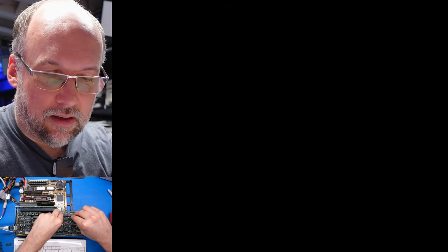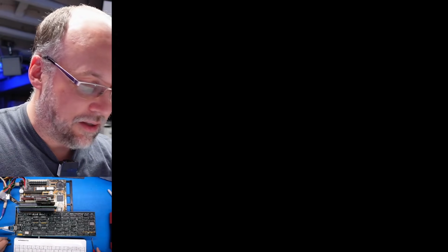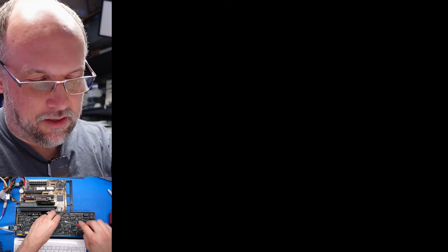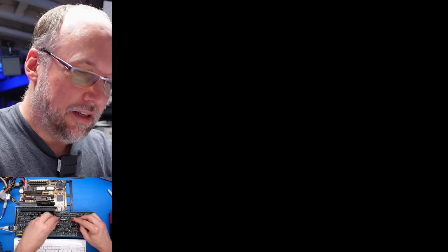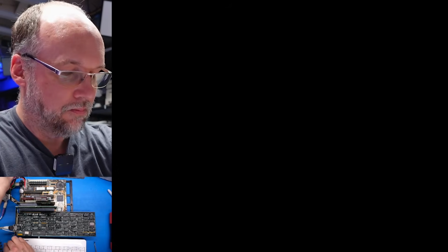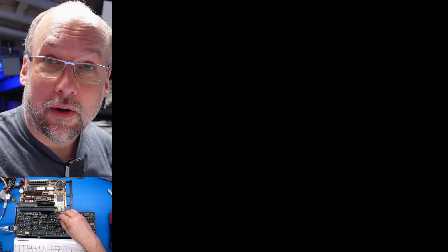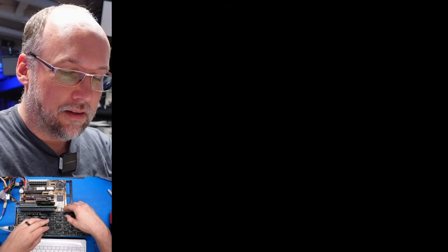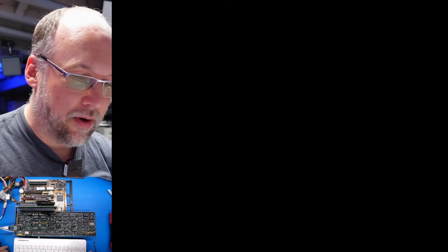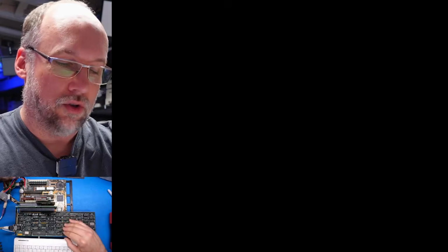So what I'm going to do now is take out 2 of these chips in pairs, and I want to see if the card can operate with really just 16K. Okay, so it doesn't operate with those 2 chips. And let's try it with these 2 chips. That didn't work. So how about with these 2 chips? I'm just sort of trying all the various combinations. No, that didn't work either. The reason I'm doing this is I really want to eliminate the parts of the board that aren't necessary for operation, so we can do this further troubleshooting. So it seems to require the 32K on this side for it to work properly.